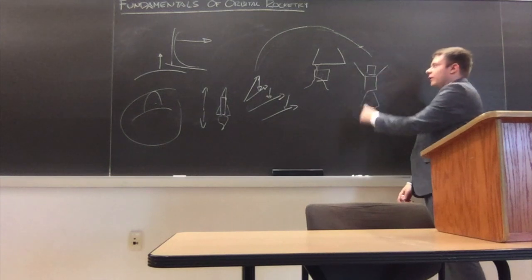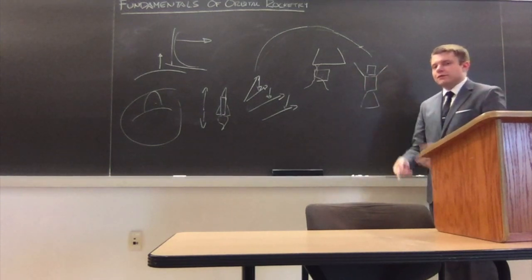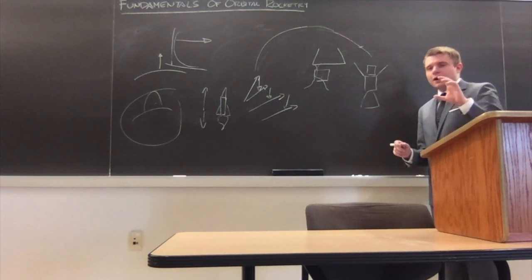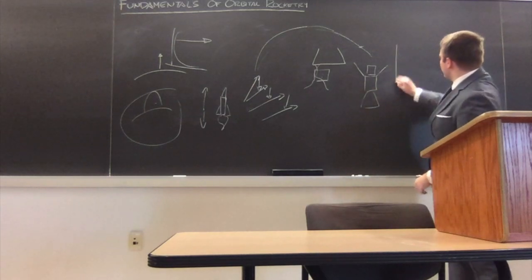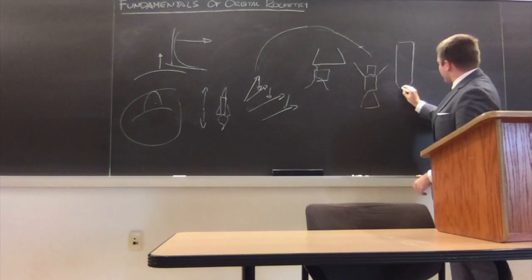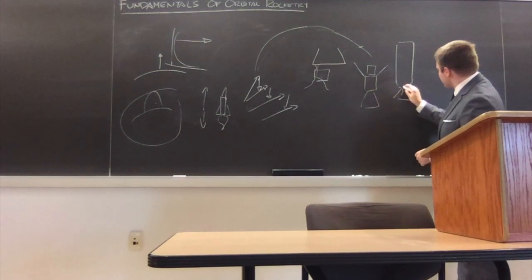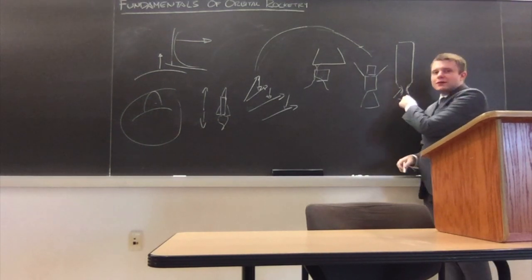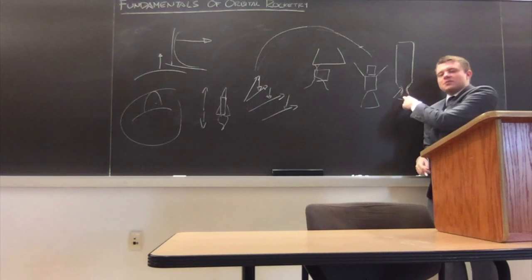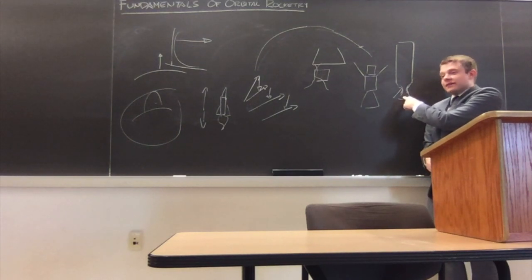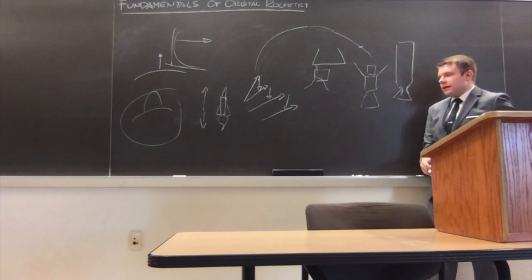You can't do this with solids because solids are one homogeneous case, and well, actually it's very hard to do with solids. And you have to actually move the nozzle. A solid motor is the sum of the propellant casing and the nozzle itself, and the nozzle itself can be made flexible. That's a really tricky joint to deal with because you're talking very high temperature gases playing in an area that doesn't like to have very high temperature gases in it. So that becomes a very huge engineering challenge.